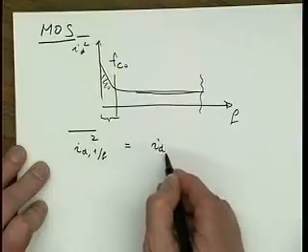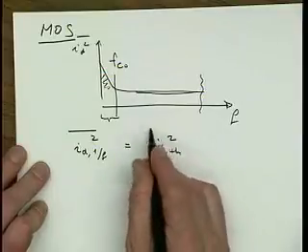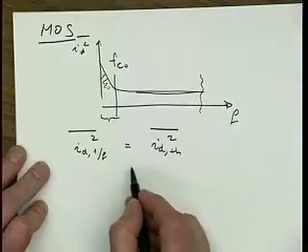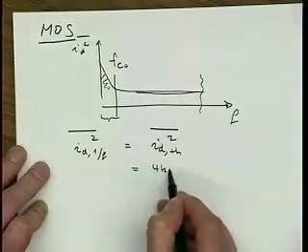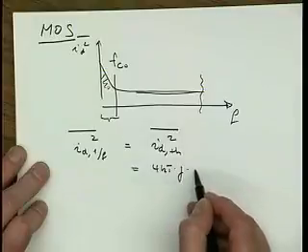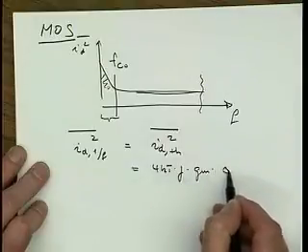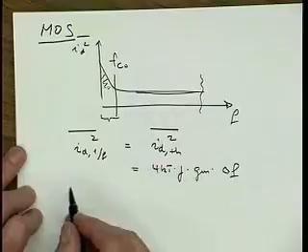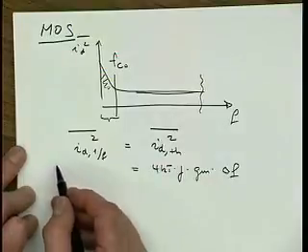Okay. So now we would like to calculate this, and for that we simply set ID 1/f square equal to ID thermal square, right? And this here was 4kBT times 2/3 or gamma times gm times delta F, and then on here we have a similar equation.